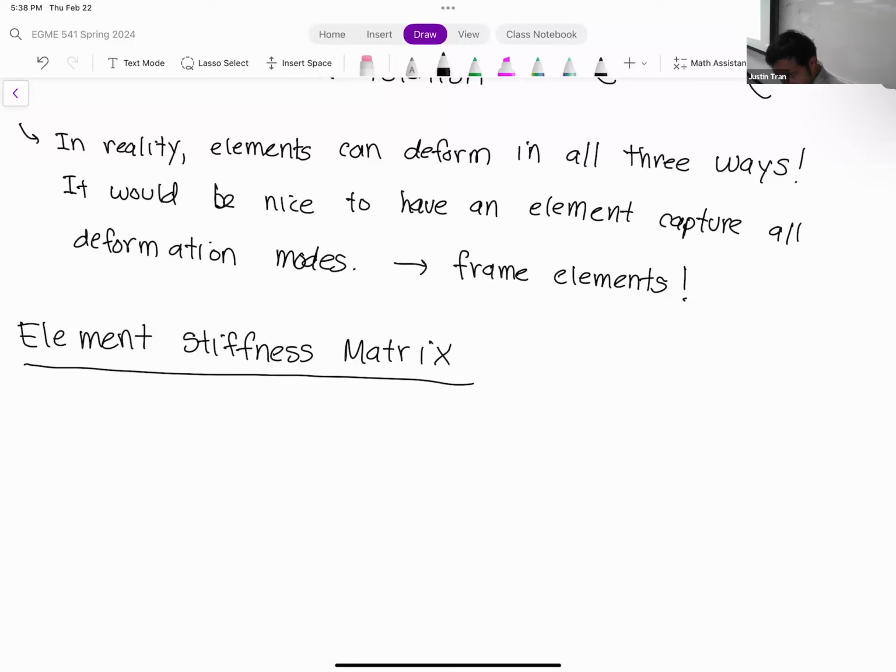There are a couple of things that we have to cover first, just because we left off the beam stuff in a weird place. The element stiffness matrix I'm going to give you for frames is arbitrary for any dimension. If you remember from trusses, we went through that whole derivation of 2D trusses, and it involves sines and cosines and things like that. So before we get to the frame stuff, let's first talk about the beam element stiffness matrix.